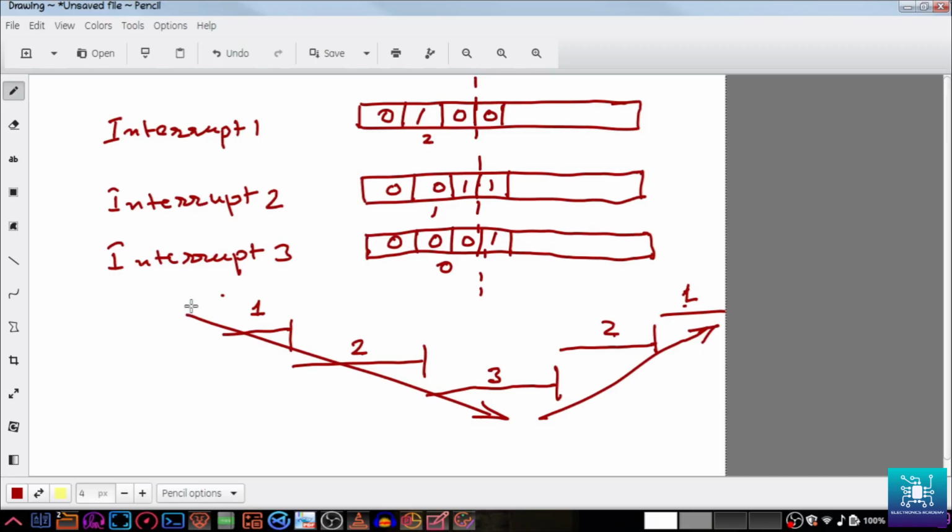Again, we see that the same thing is going to happen, because interrupt 1 again has a priority of 2. This becomes 1 because we have split up this field. This is a sub priority field, so it will not be considered within the group anymore. So the group priority now becomes 2, because we have a split. If we split it as in the previous case, the group priority is going to become 4. So this is how the calculation is done, and the group priority is based on this.